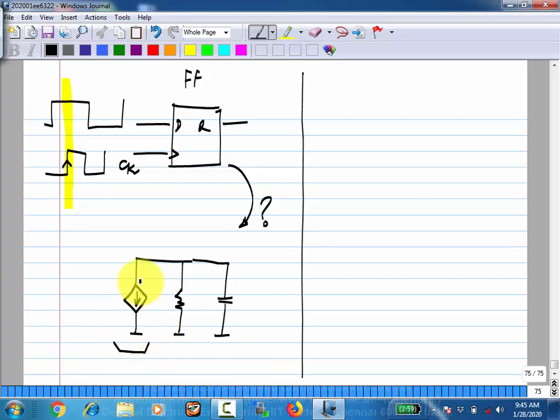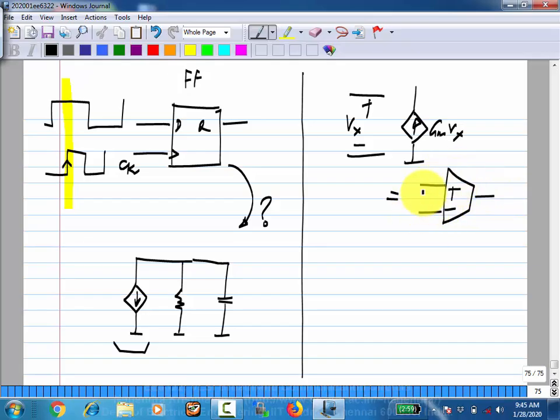By the way, I will replace this symbol with this voltage controlled current source, right? This is usually in circuit literature denoted with this symbol. It's basically an op amp with its MOS chopped off. Okay. So now let's try to make our amplifier with this, and the idea is here you have to give as much gain as possible to the signal.